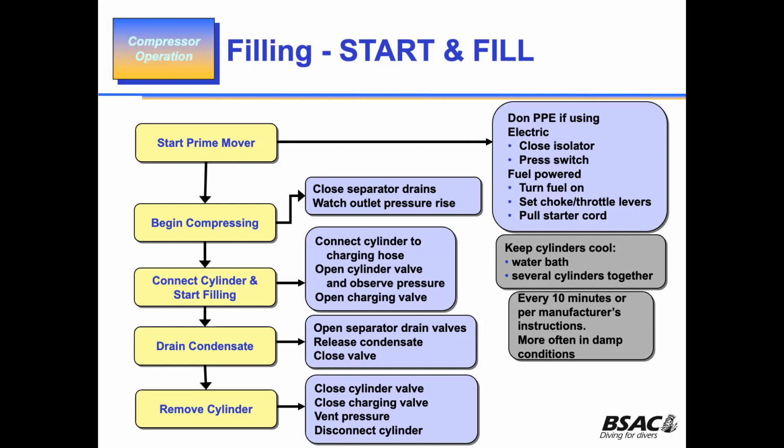All you're doing, Richard, is blowing out any moisture from that separator. The air comes in one way and then goes up over a tortuous path, and any moisture gets knocked out that way.